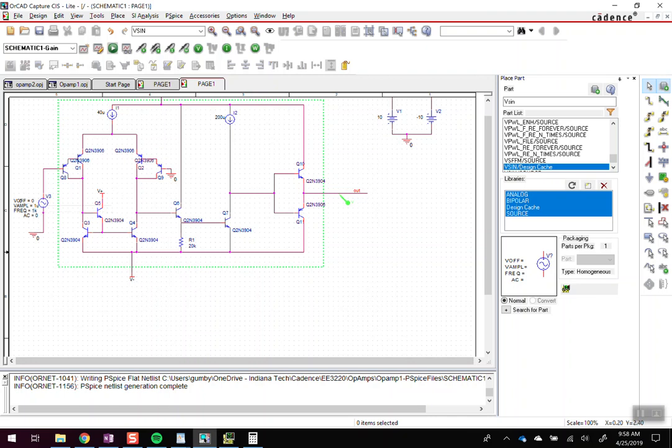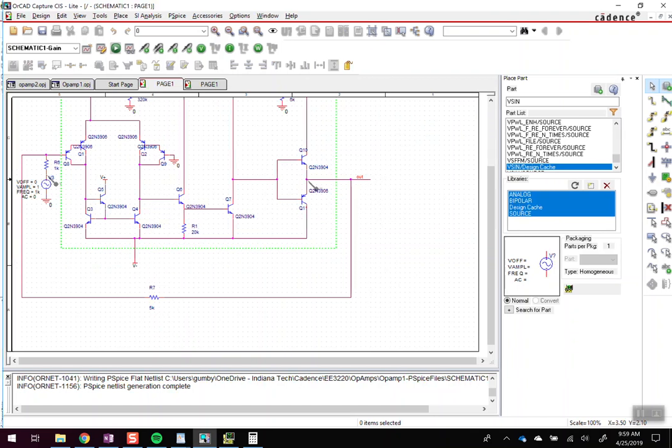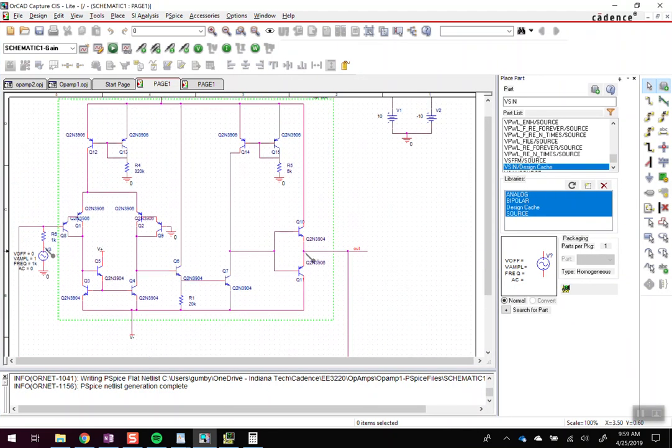Now, there are ways that you could try to simulate what the common mode rejection ratio is, because there are circuits you can build that would allow you to physically test the common mode rejection ratio, but it doesn't really work very well in simulation. So the main thing I'm going to be looking for is you calculating what large signal differential voltage gain is, and the other thing you can check, and we'll look at it in the next page, is what the gain bandwidth product would be. So what I have here now, let me show you this one here. This is a different circuit.